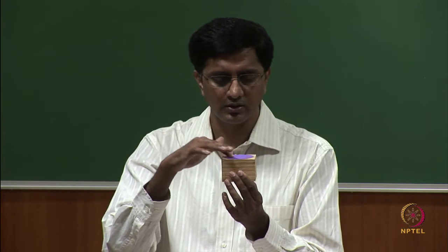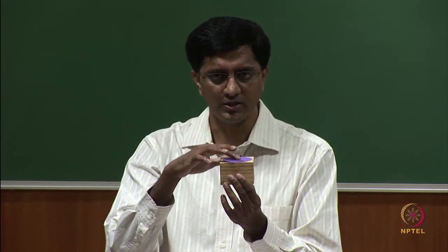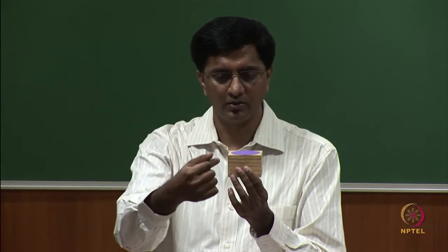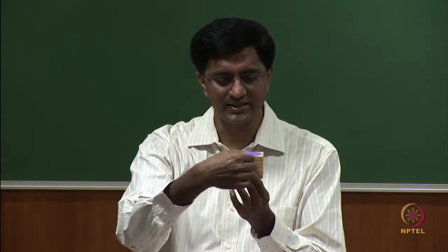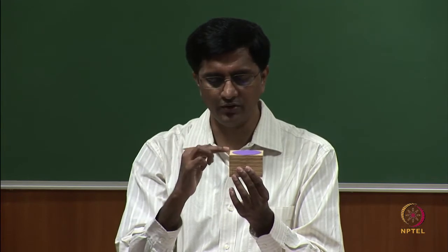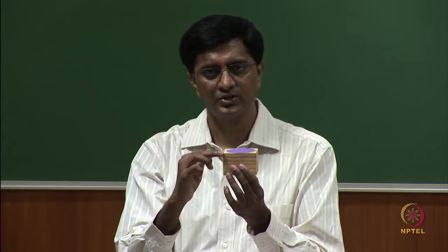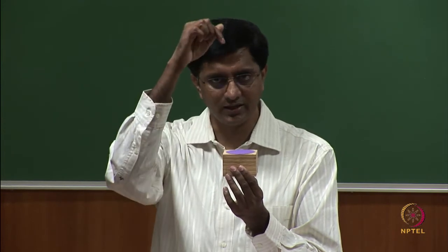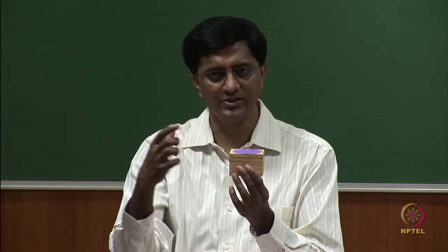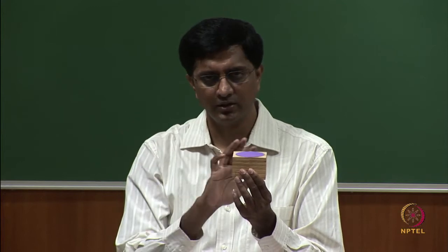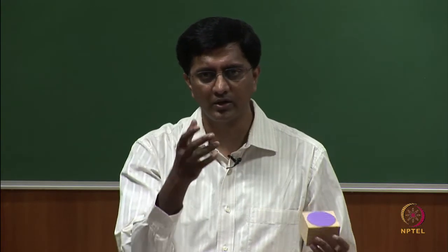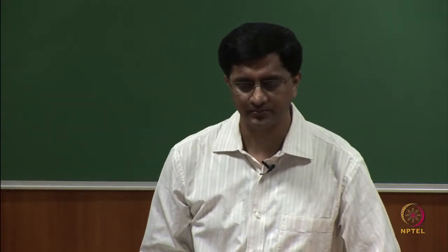This top surface of this object, only in the top view it is captured as an area, but in the front view we only see this edge, and also in the side view we only see it as an edge. So, which means this surface is captured as an area in one view and as an edge in 2 views.